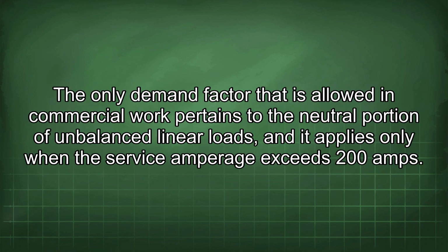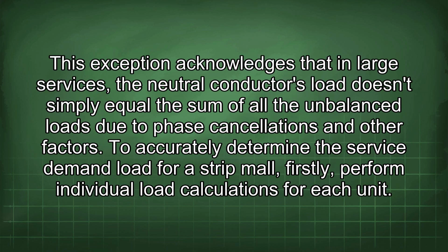Each unit's calculated amperage contributes directly to the total service demand. The only demand factor that is allowed in commercial work pertains to the neutral portion of unbalanced linear loads, and it applies only when the service amperage exceeds 200 amps. This exception acknowledges that in large services, the neutral conductor's load doesn't simply equal the sum of all the unbalanced loads due to phase cancellations and other factors.